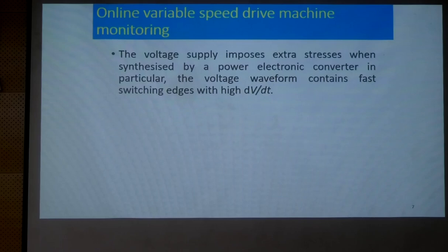That's where the insulation of inverter fed motors has to withstand very intensive stresses, and thermal stresses also. Even in the International Electrotechnical Commission IEC standards, they mention that conventionally we are going for AC sinusoidal, but now we are going towards PWM switching using such devices.